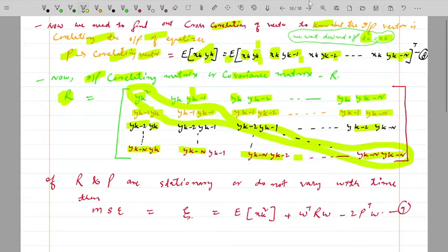Basically the diagonal part is the correlating part, and this matrix has information of the input signal transmitted from the transmitter. All other components we don't want; we only want the identity form matrix, or only the diagonal component of this covariance matrix.